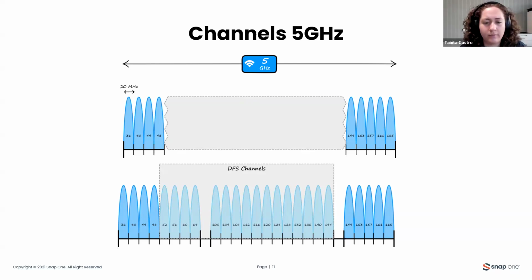Yes, Tabitha. One question. How do you know, or what tool do you use to know if there's any radar or something in the DFS channels? So you should use some kind of Wi-Fi frequency analyzer in order to detect what the frequency spectrum looks like in that area.